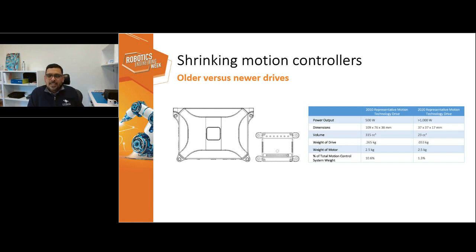And obviously we packed the amplifier in this. So it has everything: the motion control, a host processor, and the amplifier that you need to control a motor. There are a lot of man-months that have gone into making the amplifier as small as we can. And obviously heat's a concern, so we packaged it in such a way that you could run up to 20 amps of current with no issues in this drive.